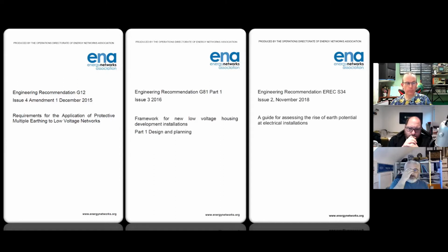As you know, Dave, for the last 2 months, I've made understanding networks my day job, night job, evening job, and morning job. It's a work issue. So anyway, G81, Part 1, framework. If anybody here is working in construction and you're asked to go on price for a new build estate, go to G81, Part 1, framework for designing and planning a new estate. So how you would do the earthing, it talks about solar PV connection, EV connections, all that good stuff. How you do the earthing, it's in these documents and they are free.